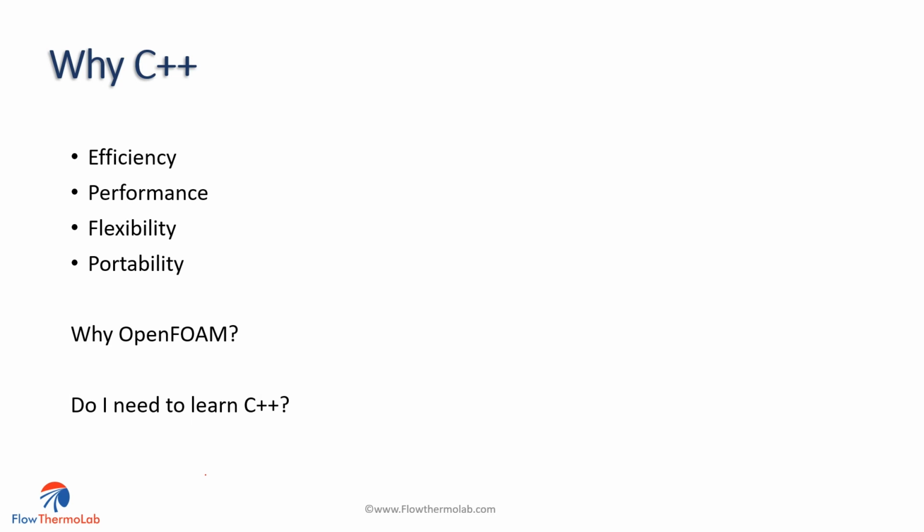And I think the last question, and we covered this at the start, do I need to learn C++ to be able to code in OpenFOAM? And technically, no. If you wish to just change something simple like a constant value in some piece of code, then obviously no. Perhaps you want to just modify the constants in a boundary condition. That's quite basic stuff. It doesn't require you to understand C++. You just have to open up a text editor, change some values, and recompile the code, much like you would when you install OpenFOAM for the first time.